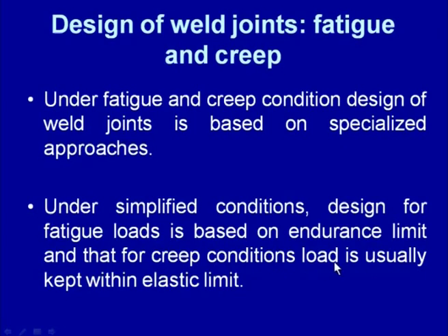While in the design for creep conditions, the load is usually kept within the elastic limit, but further for this case we need to see what is the allowable deformation which can be used for identifying the creep life of the component.